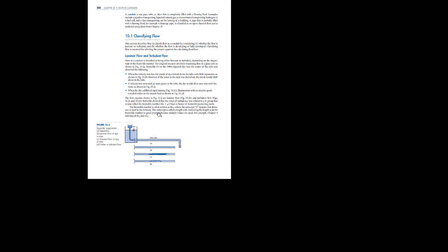But just imagine if the pipeline diameter is very small, like 2 millimeter, and you are flowing a very viscous material, for instance honey, and the velocity is very low. Then you will get a sharp-ended velocity profile, and that is totally a laminar profile. We have seen this difference back in our ANSYS simulation, right? So these are the main differences between laminar and turbulent flow.